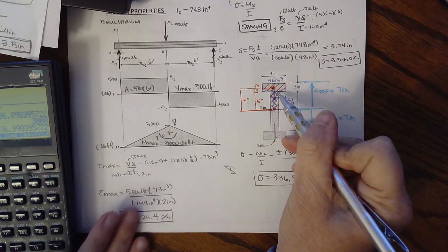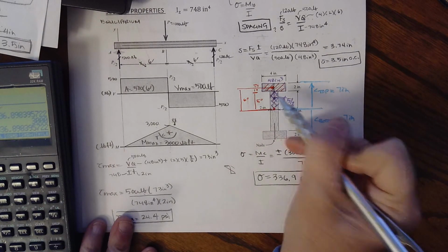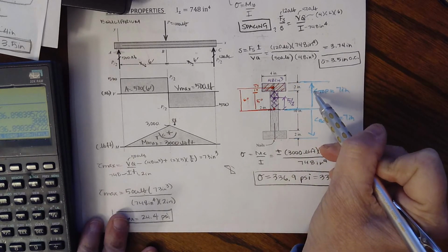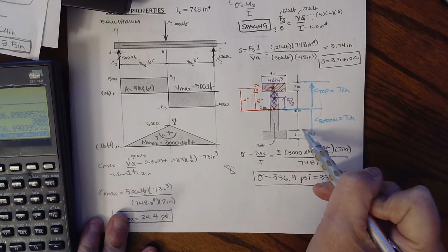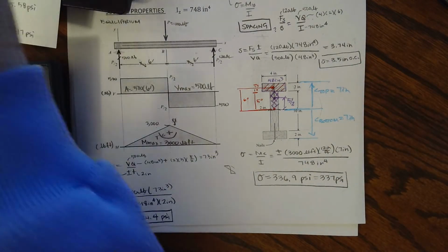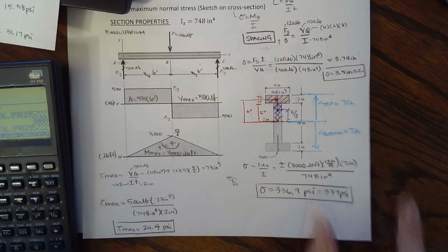Our shear stress we actually could do because we've already have this Q from putting our fastener on, and we know it's going to come down, then have a big jump because of thickness change, come around, big jump down, and there you have it. So it's really a matter of learning what these rules are.